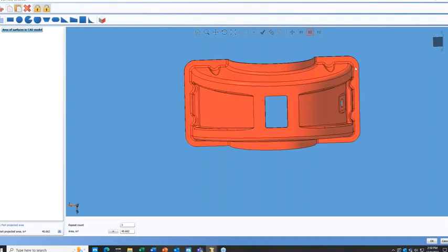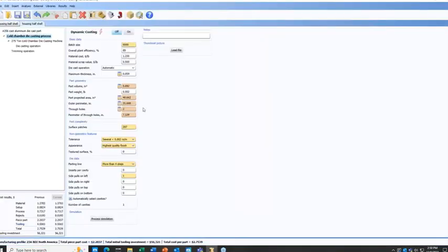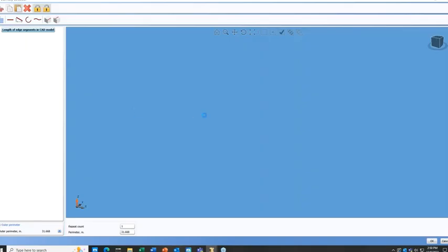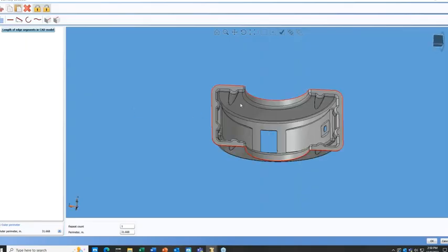I've specified all of this area that's shown in red, and I've projected it on the XZ plane. That gives me a projected area of just over 40 square inches. My outer perimeter, I've also defined using the CAD model, as this perimeter shown here in red.